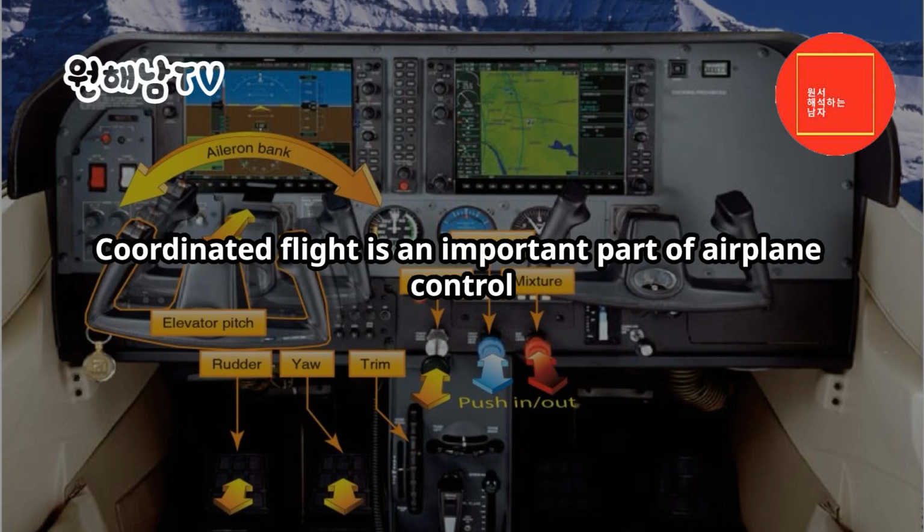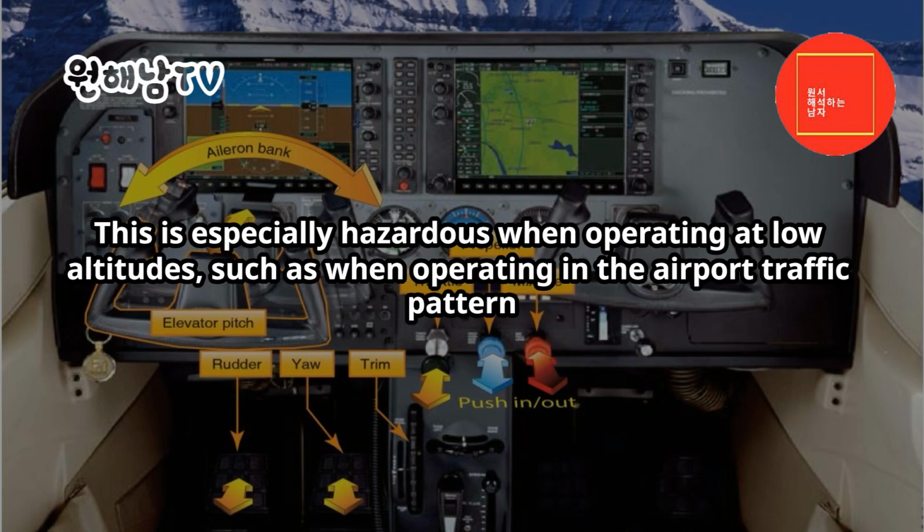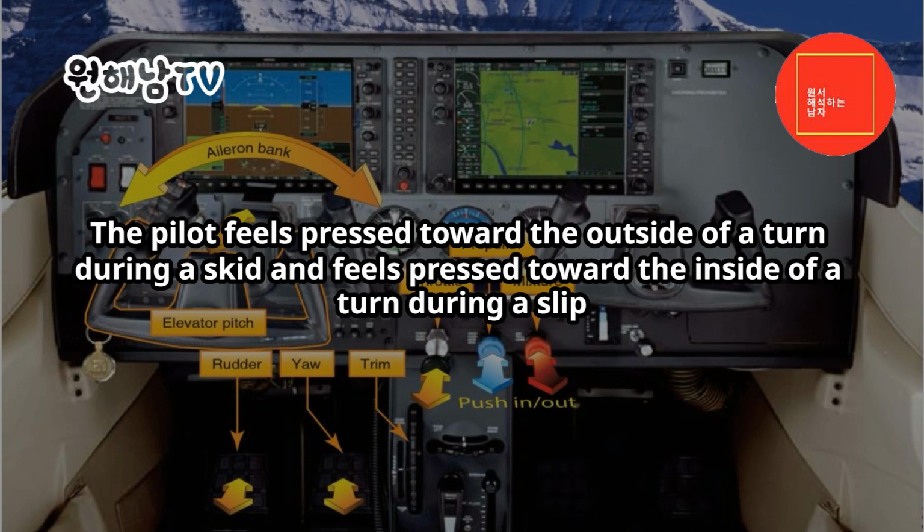Coordinated flight is an important part of airplane control. Situations can develop when a pilot maintains certain uncoordinated flight control deflections, which create the potential for a spin. This is especially hazardous when operating at low altitudes, such as when operating in the airport traffic pattern. During uncoordinated flight, the pilot may feel that they are being pushed sideways toward the outside, or inside of the turn. The pilot feels pressed toward the outside of a turn during a skid, and feels pressed toward the inside of a turn during a slip.